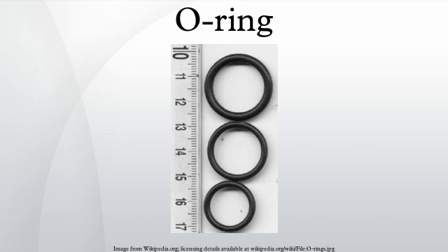There are also rings with a square profile, commonly called square cuts, lathe cuts, or square rings. When O-rings were selling at a premium because of the novelty, lack of efficient manufacturing processes and high labor content, square rings were introduced as an economical substitution for O-rings. The square ring is typically manufactured by molding an elastomer sleeve which is then lathe cut. This style of seal is sometimes less expensive to manufacture with certain materials and molding technologies, especially in low volumes.